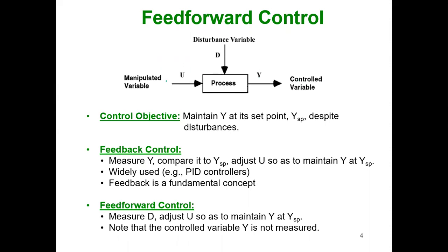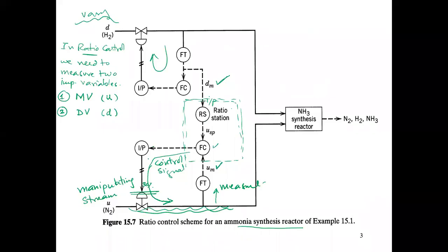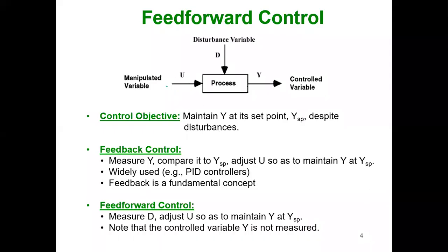And basically behind that process we are manipulating a few things. For example, we might have access to a pipeline like this one, which we can change. So we have access to the changing of this. This is called the manipulated variable, and then we have the disturbance variable. So we have three things: D, U, and Y.